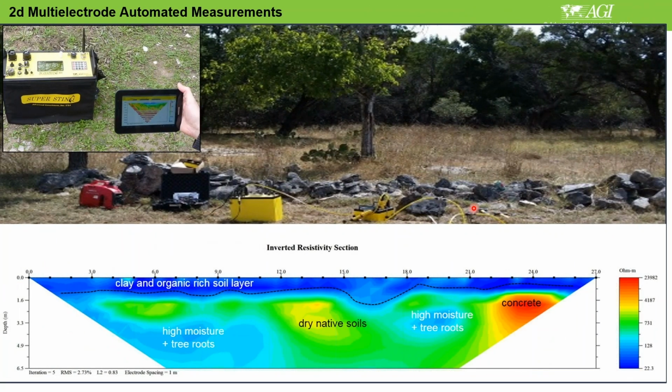So then typically what you get is these 2D sections. Okay, so these 2D sections, and really what you're trying to get is what is under the ground. If I do this 1D electrical sounding, or like a 4-electrode measurement, Schlumberger sounding, you will not get any lateral variations. You will not get the variations under the ground.